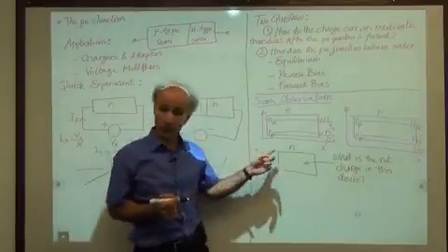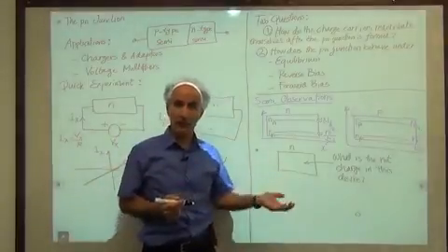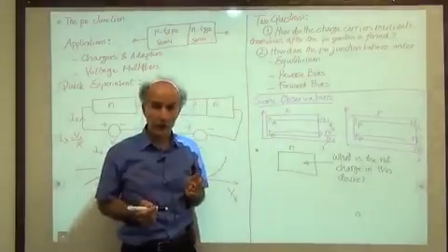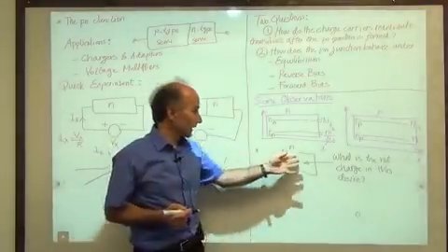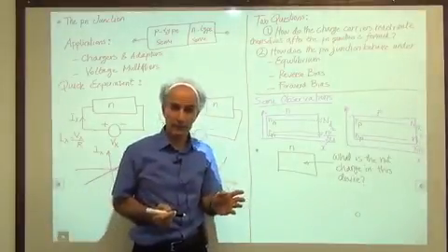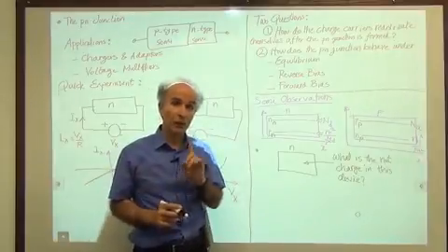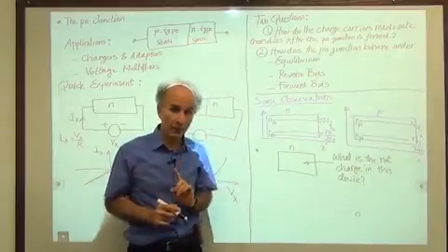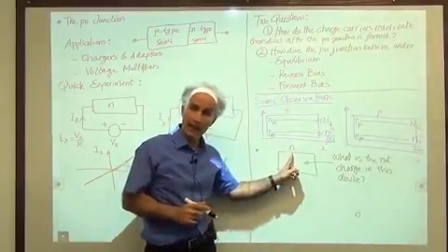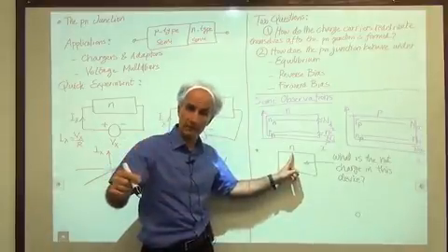Well, we said we have lots of electrons, very few holes. So does it mean that the net charge in this piece of silicon is negative? No, it does not mean that. Remember that this n-type material just consists of silicon atoms and phosphorus atoms, and nothing else. We didn't do anything else. So we still have charge neutrality because every electron that is present here has one counterpart proton in the nucleus of an atom.